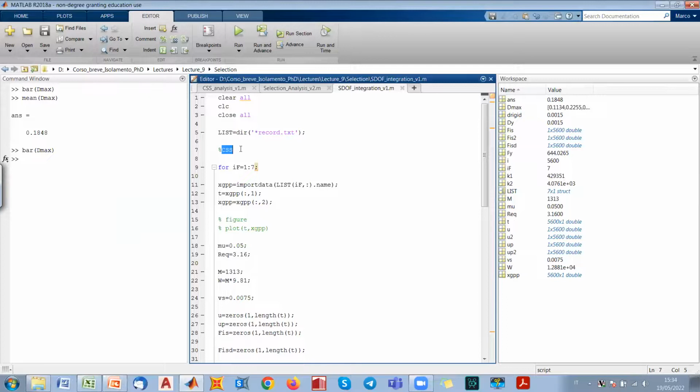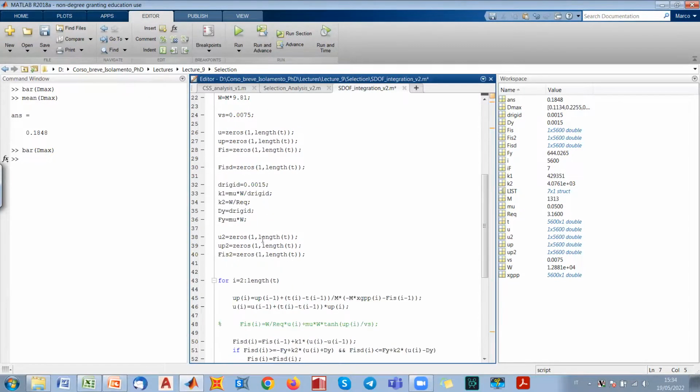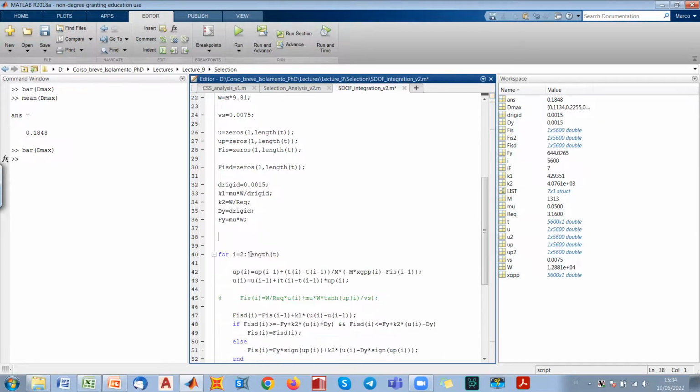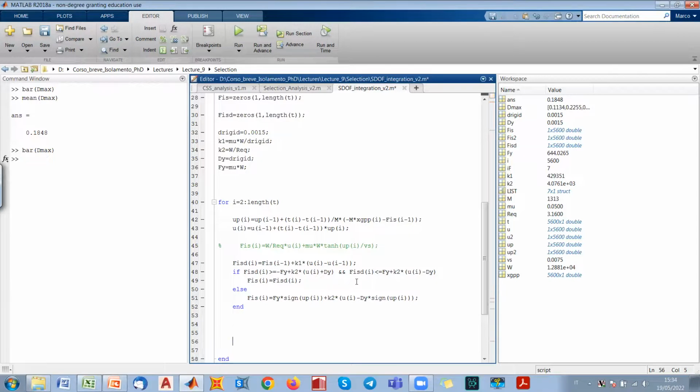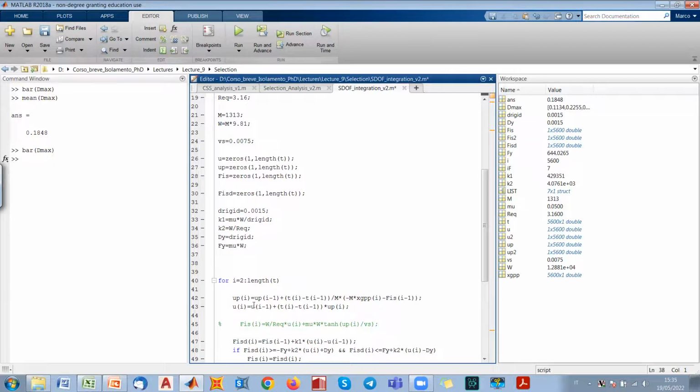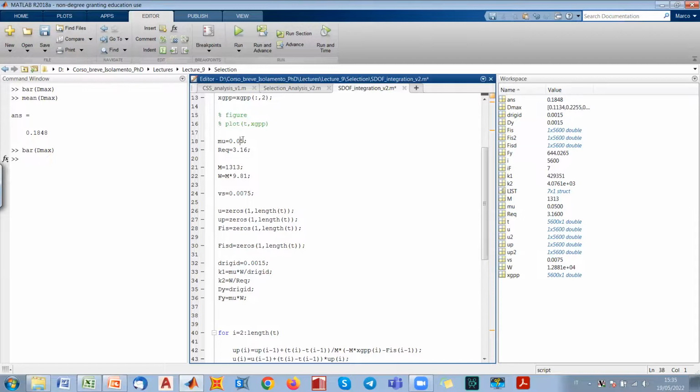Let's save as, starting from the lead rubber bearings. Okay, and then we have just to modify. We don't need the hyperbolic tangent again, maybe. Or we can use it just to model also flat sliders. Simply because, if you remember, lead rubber bearings were just 4 over 24 supporting points of the overall building. So maybe it is better to also model that. So this is to model the isolation force just related to lead rubber bearings. And then we can also try to model the characteristics for flat sliders. I will have to change some properties. These, okay, let's erase these just because we need pure friction.